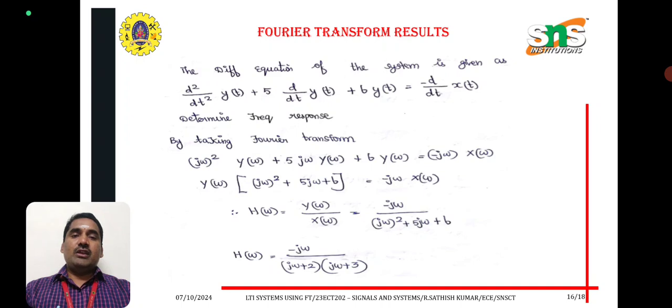Now we can take Y(ω) as common outside: ((jω) square plus 5 into jω plus 6) into Y(ω), which is equal to minus jω into X(ω). Therefore, H(ω) is equal to Y(ω) divided by X(ω), that is, minus jω divided by ((jω) square plus 5 into jω plus 6).